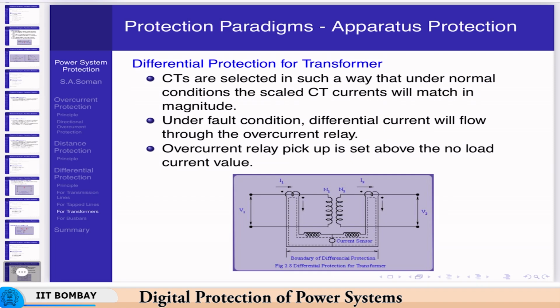So here, if you remember your dot convention, the current I1 is entering here at the dot. So 5 amperes will leave at the dot as shown. Similarly, if I2 is entering at the dot, then 5 amperes will leave here. So you can see that a circulating current of 5 amperes is being set up, which is shown by the dotted line. Okay. So there is a circulating path here for the circulating current. The actual current, of course, will be I1 into 5 by 100, and here on the right hand side it will be I2 into 5 by 1000.